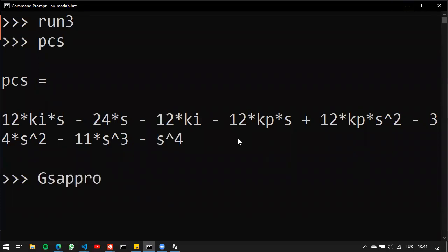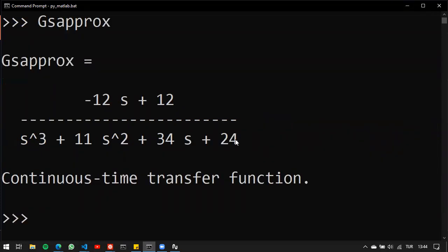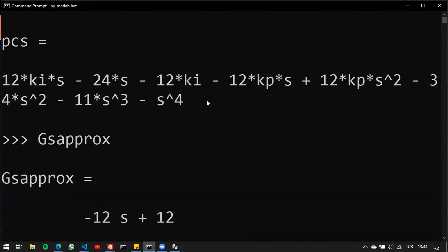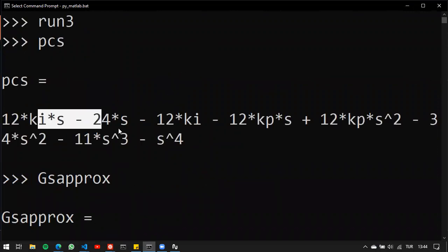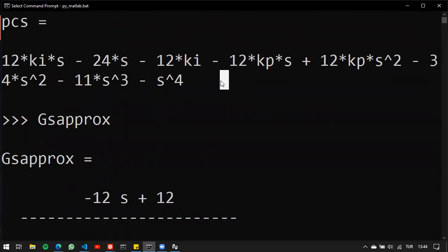So let me just quickly check. Yeah. Since we have also the controller itself, you can see that the approximation did add 1, the controller adds another 1. So therefore we have a fourth order closed loop. So you can see that even using a first order approximation gives us much trouble because we have a fourth order one. If we increase the order, it will get worse.